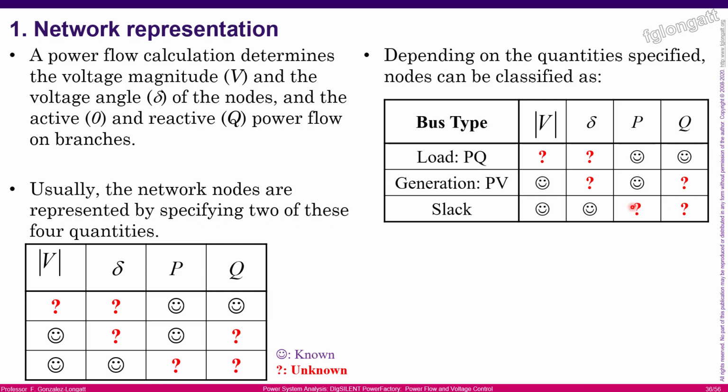variables are the active and reactive power, and these have an extremely important effect when you are calculating the steady state condition or the power flow of your power system, because you must realize that the slack bus bar is the bus bar coping with all the losses inside your power system. If you remember, the balance equation says all generation is equal to all consumption plus the losses. If you have PQ bus bars, in all of them you know P and Q. And if you have some generation PV bus bars, you know P. That means that the only bus bar where the active power P is unknown is the slack bus bar. As a consequence, all the active power losses and reactive power losses will be covered by the slack bus bar. That is the reason some people call this the bus bar for compensation.